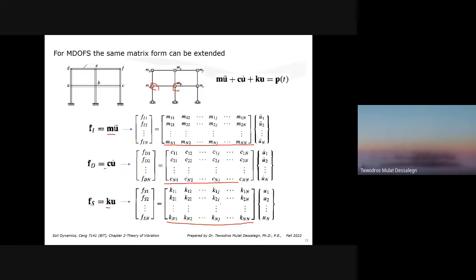It's the same as when we saw the 1 degree of freedom system, we calculated it by hand. It was easy. We can put it in Excel or MathCAD and solve it. When it gets to a multi-degree of freedom system, it's the same philosophy, but the equations get bigger. The solution is becoming more realistic, and we need computers to solve it now. But the general dynamic equation is always valid. Whether you use SAP 2000, STAAD Pro, even geotechnical software like FLAC, they are always solving the dynamic matrix, the general equation of motion.